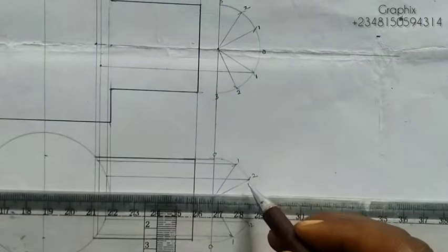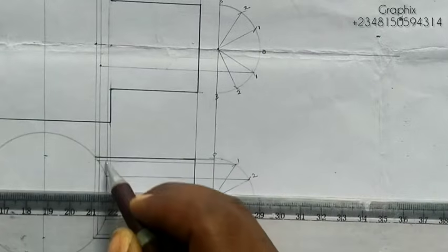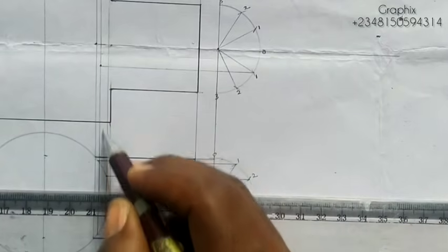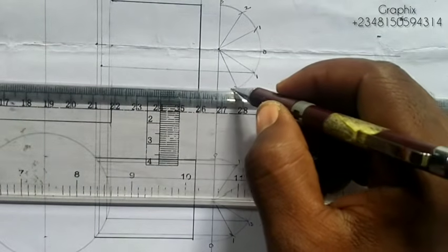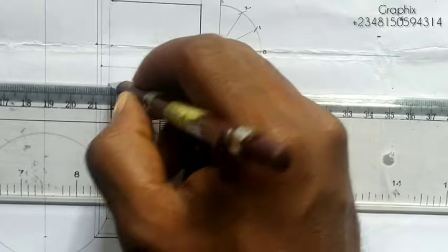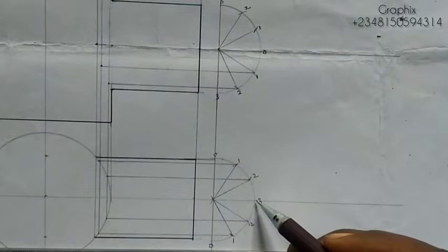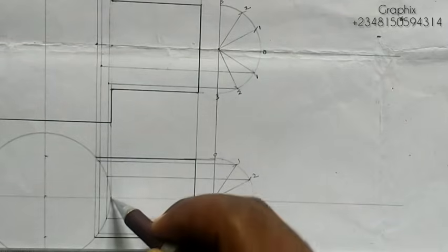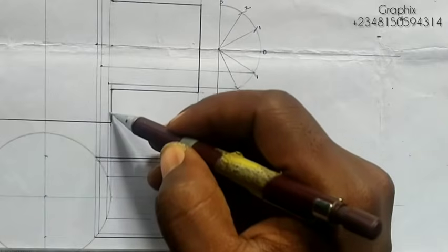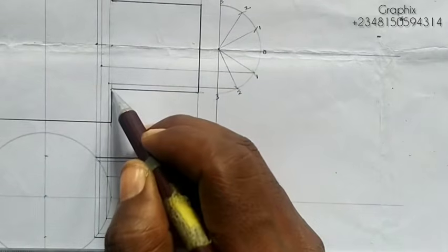Right? Go to the next one too, which will be 2. This is 2. Where it meets the circumference of the circle, it meets it here, right? And it's going up here. So this third line is for 2. So I'm going to project 2 on this point. Where 2 meets 2 is here. Right? The next one is 3, which is line 3 here. 3, where it touches the circumference of this circle, it touches here. And it's going up. So this is where it is. So where 3 meets 3 is at this point.